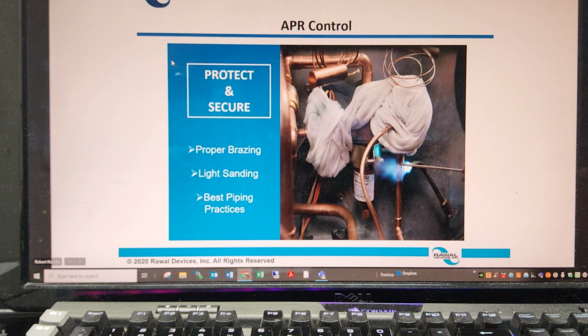And also, a light sanding is all you're going to need on the valve connections. They are a copper-coated stainless steel, and over-sanding can result in a failed joint. No, we probably won't sand it. It's not necessary. All right, perfect. Unless you're telling me something I don't already know. I've been doing this 30 years, but I'm always willing to learn. Are you saying light sanding kind of roughs it up a little bit so the solder will flow better? The Silfoss? Yeah, it's just got to rough up that coating a little bit. Okay. And it'll just flow a little bit better. Got it.